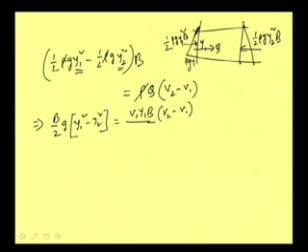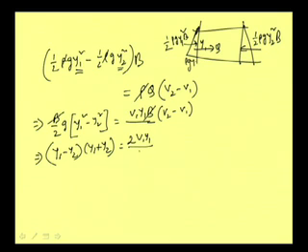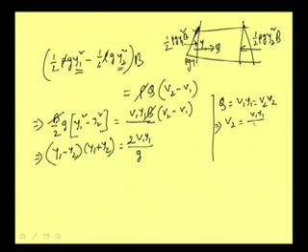Now again we can cancel b and b, and write it in this form: y1 minus y2 into y1 plus y2 is equal to twice v1 y1 by g, and then v2 minus v1. From the continuity equation we have q equal to v1 y1 equal to v2 y2. So v2 can be written as v1 y1 by y2.